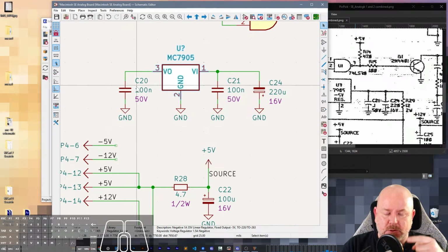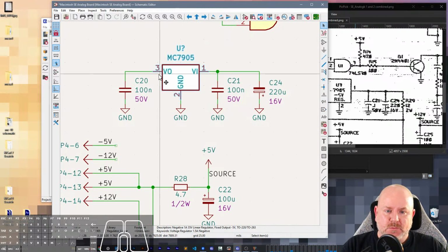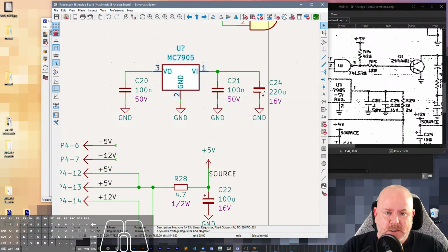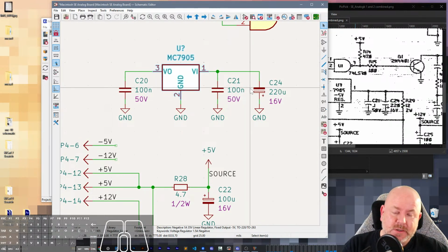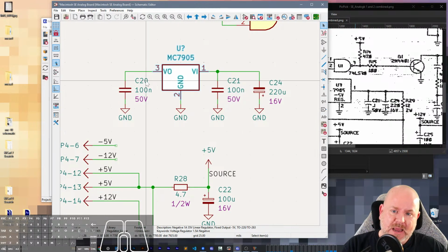It should be closer to the load so that the regulator can, in its very short loop, regulate the voltage of the rail. What you do want is a big decoupling capacitor on its input so that as it's dealing with fluctuations on the input, it can handle it.